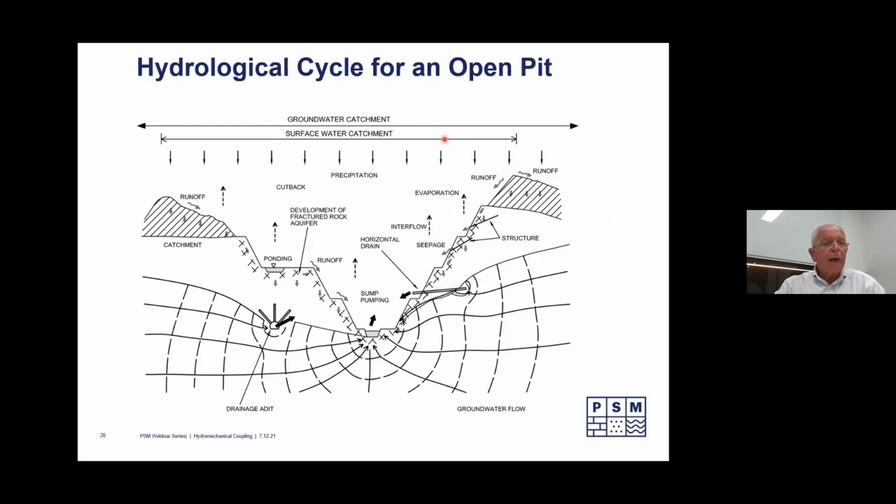So this rainfall that's happening from the surface water catchment, the precipitation gives us runoff, infiltration through the upper materials, infiltration through the near surface zone of the excavation itself. And a lot of that ultimately reports to the groundwater table at depth. And then we might have some other structures within that that hold water temporarily, like a sump in the bottom or on a bench. All of these elements can play a role in what's happening.